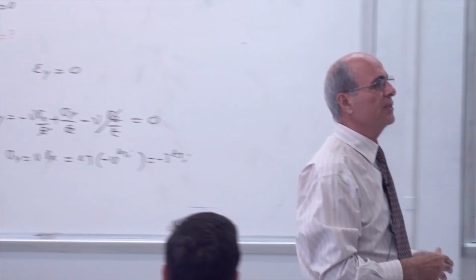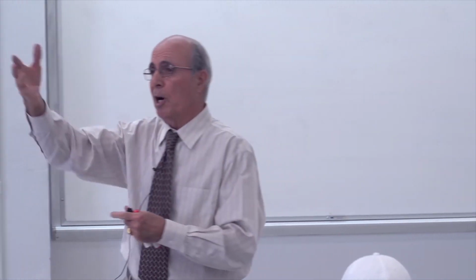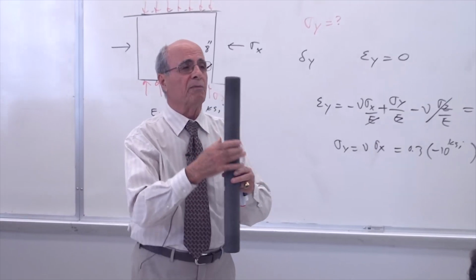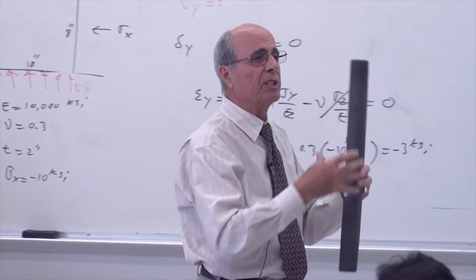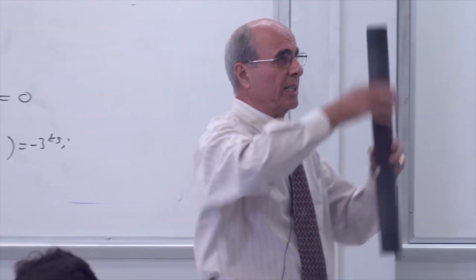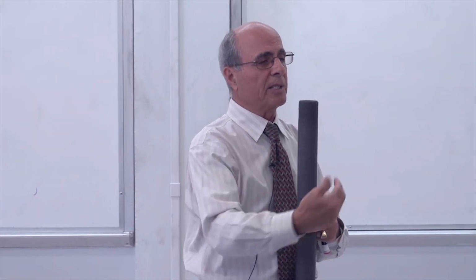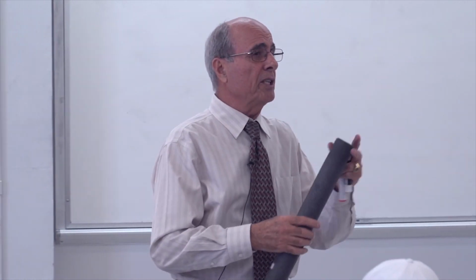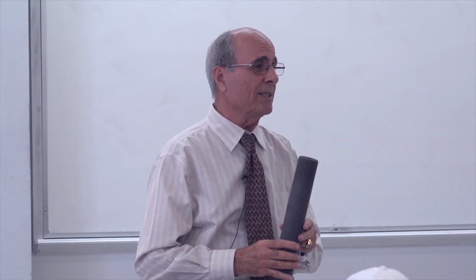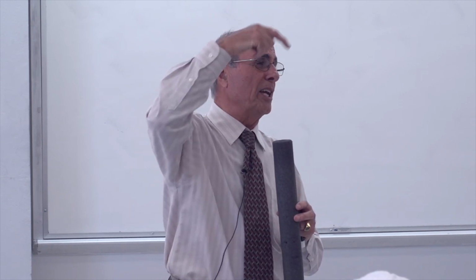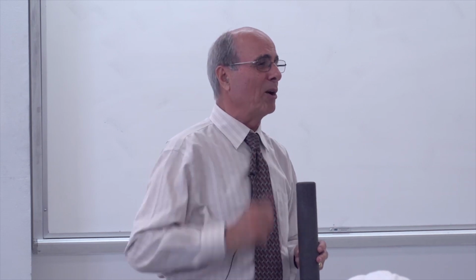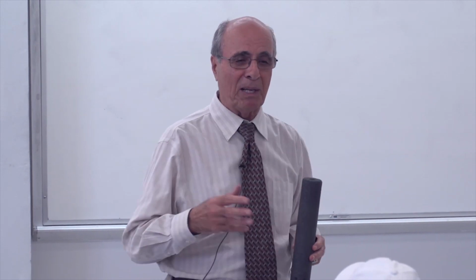Is that understood? Yes? Okay, you have another pipe, the gentleman back there. So in the pipe, what was your conclusion? When this part of it is under pressure, there is no sigma, let's assume this is y, there is no sigma y. Is there a sigma x? Is there a sigma z? So that's it. Now notice I have given the same problem on the quiz. On top of that, I put here a tension. Can you do that? There is a sigma y as well. Everybody understands? So it becomes effectively 3D.